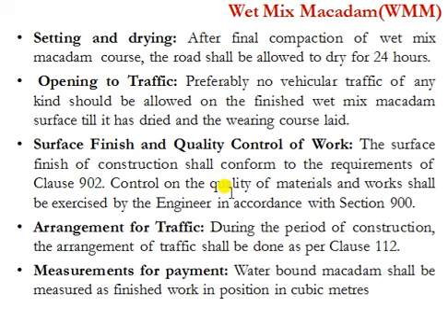During the period of construction, the arrangement of traffic shall be done as per clause 112. In clause 112 of MORTH, it is specified that alternative ways should be provided for the movement of traffic.